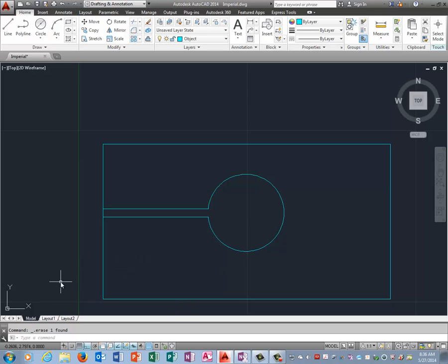Now I need to start putting these angles on this thing. And it tells me that the angle that goes this way starts at 1.06 over. So I'm going to offset 1.06. Okay. And now it tells me that this is a 60-degree angle that makes this cut through the whole thing, which is wonderful. So I'm going to do line. Click here. I'm going to press shift and touch comma on my keyboard, and it gives me the little carrot looking thing right there. This is 60 degrees, but it's 60 degrees plus 180 because this line here is 180. So that's going to be 240. And then I can just draw my line.